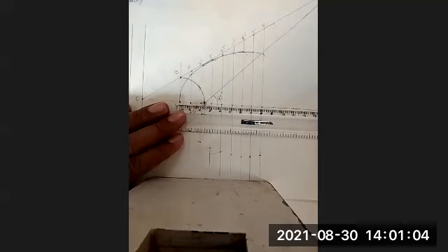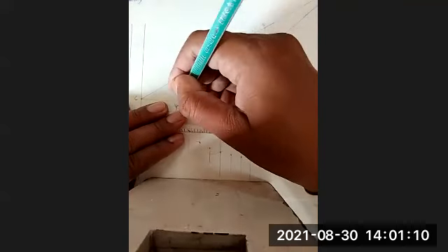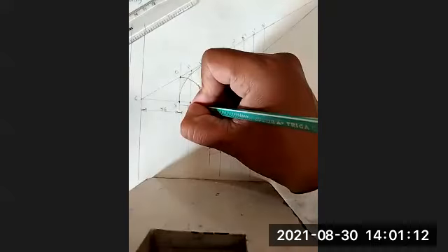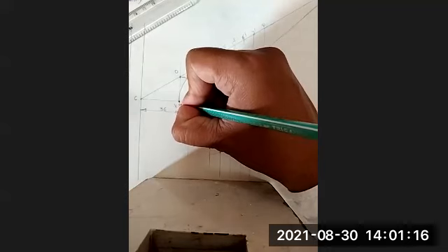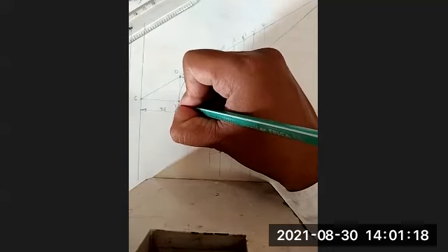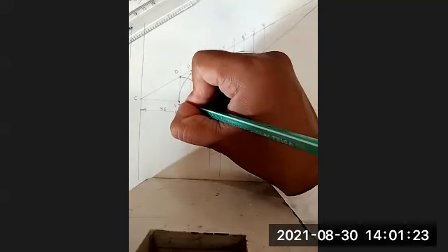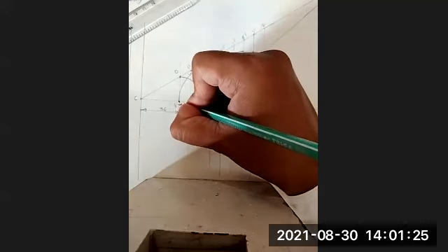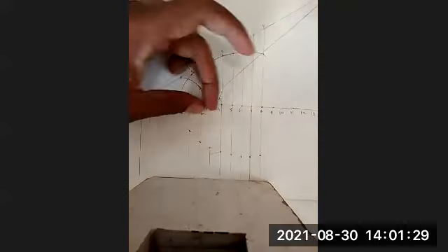Okay, so here intentionally I have chosen this 10 millimeter. But in the case of a parabola or hyperbola, because that is an open kind of curve, it is better to go with 5, 6 millimeter spacing. But in an ellipse you can take it a little wider. So this spacing I have taken 10 millimeter, so each 10.